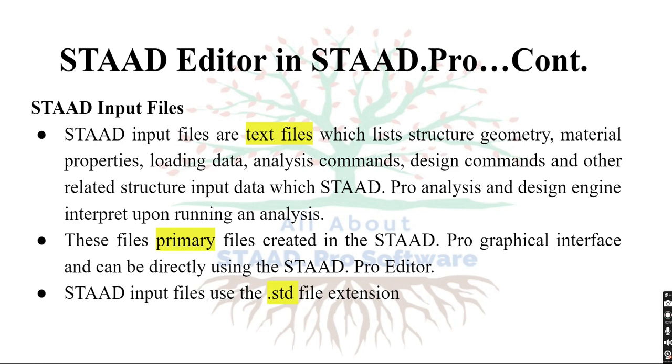And we can change the STAAD editor or the input files. We can change the data by typing, and we can do the analysis part or run an analysis. These files are primary files created in the STAAD Pro graphical interface and can be edited directly using the STAAD Pro editor. These input files use the .std file extension, or these files are saved with the .std file extension.